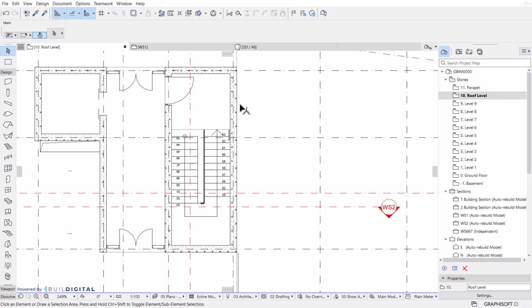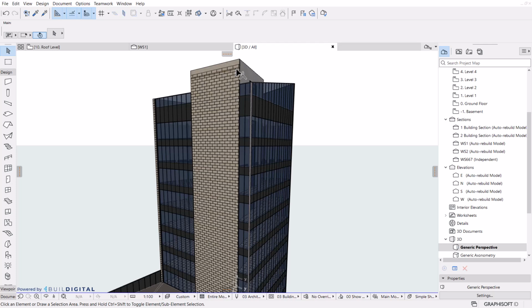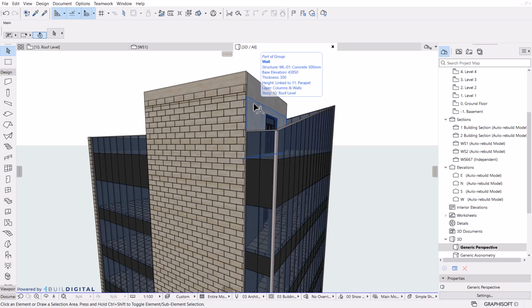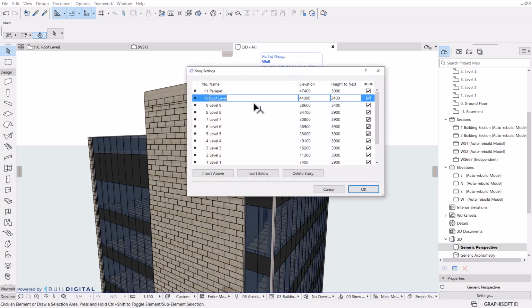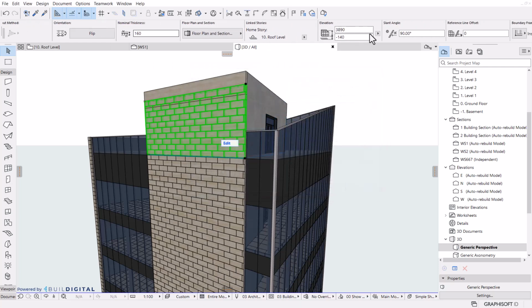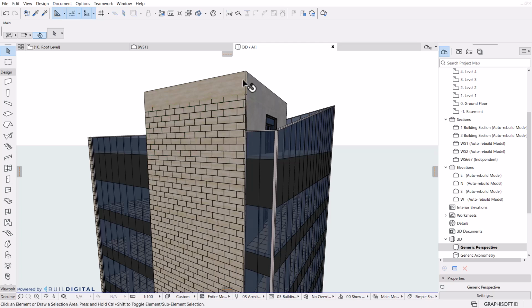get rid of the existing wall, paste it, go back to the 3D view, and let's check the height. Now that height needs to be adjusted. Currently, that roof level is at 3 meters and 400. So the curtain wall then needs to have 3 meters 390. Again, leaving the 10 millimeter gap we need for the wall and the cladding that will start right above.